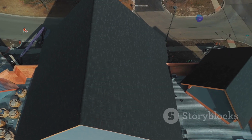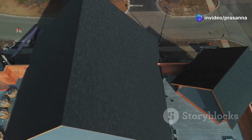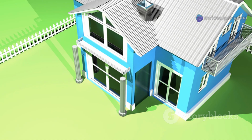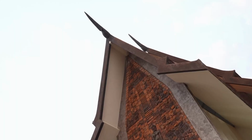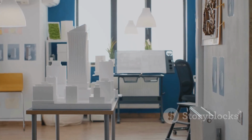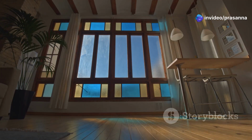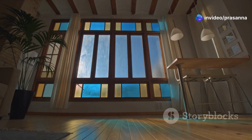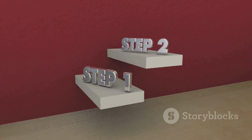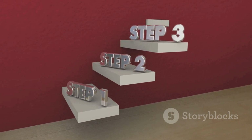Experiment with different methods to find what works best for your design. Always ensure your roof overhangs the walls appropriately to protect them from rain. This detail adds realism to your model. With the main structure and roof complete, it is time to add openings for doors and windows. These elements bring light into your house and connect the interior with the exterior. You can use the Rectangle tool to draw the shapes of doors and windows directly onto your wall surfaces.